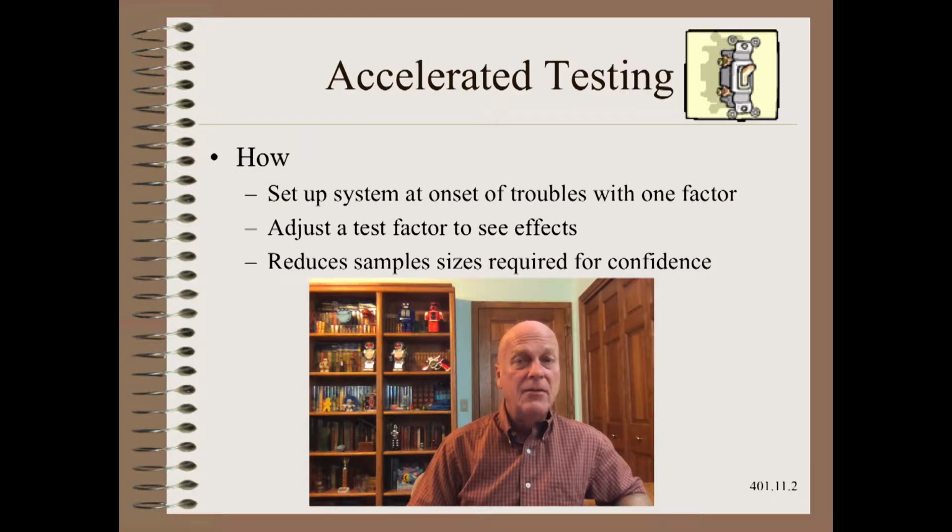An example here from web handling is web breaks per roll on a newspaper printing press. Breaks are typically a couple of percent. With defect rates of 1 per 100 rolls, trial sizes may need to be as high as 1,000 rolls to be statistically solid. If, on the other hand, the rate is too high, we could get buried in trouble.